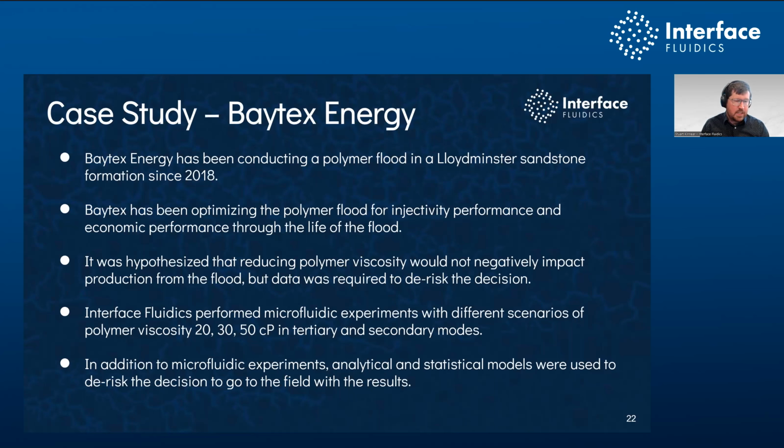So the background here is that Baytex has been conducting a polymer flood in their Lloydminster sandstone formation since 2018. They've been optimizing this polymer flood for injectivity performance and economic performance throughout the life of this flood. And the hypothesis that they had was that reducing polymer viscosity would not negatively impact production from the flood after it had been aging for a period of time. But this is a costly and expensive change to make, and so they were seeking additional data to understand how the behavior would change if they changed viscosities.